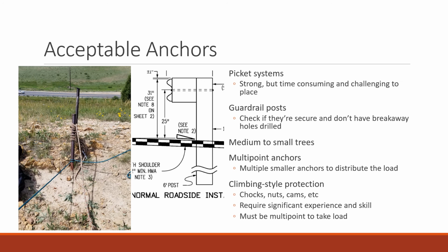Finally, you have the option to use climbing style protection. So chocks, nuts, cams, things like that. Things that climbers would be placing as they advance up a rock slope. The big caution here is that these require a lot of experience to place successfully. They can be strong, they can be effective. You're probably going to have to make them multi-point, but they can be the best way you can put an anchor exactly where you want it by using these tools. So take some time if you're going to get into that and study it with experts and practice, obviously before you're subjecting it to live loads.